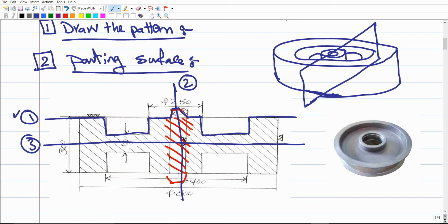Because it will be difficult for the molten metal to go up. It is easy for the molten metal to spread in the X, Y, or Z direction, or going down. It's going to be much easier for the molten metal to go down than going up. So in case this one is vertical, pushing the molten metal to fill the top part of the casting would be hard, and in this case we would end up with some problems and defects in the casted product. So that's why it is advised for this product, especially this one with this wide shape, to be casted in the horizontal position.